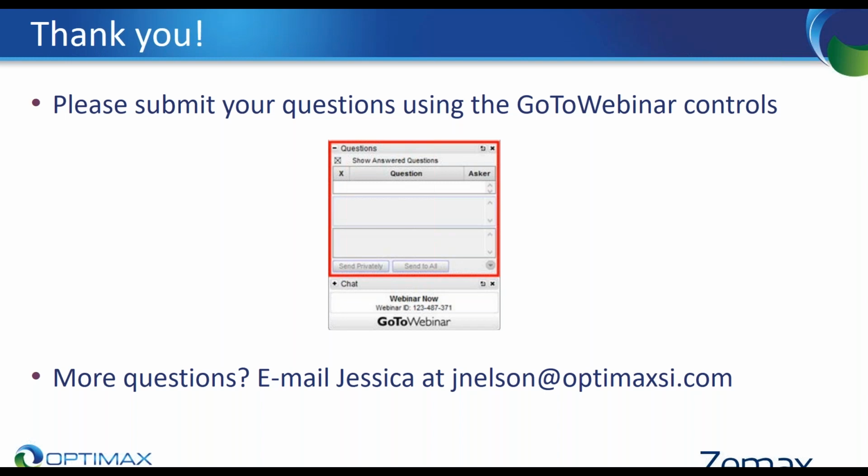What it does is use the Zernike residual RMS and minimize the effect of residual, or I would say spurious, errors that can result with a traditional peak to valley measurement. As I mentioned before, when you're just using two values or two pixels, if you have a piece of dust or a bad pixel or a hot spot on your transmission sphere, it may cause an error in your measurement.